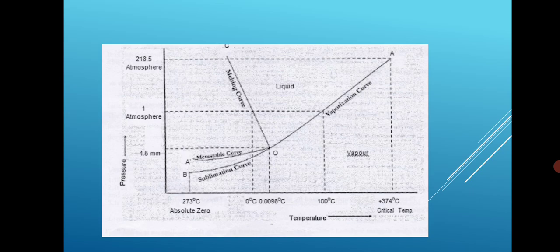In order to define the system at any point in the area, it is essential to specify both temperature and pressure. Therefore, the degree of freedom of the system is 2, bivariant, along these areas. When we put the values of C and P, we get F equal to 2.